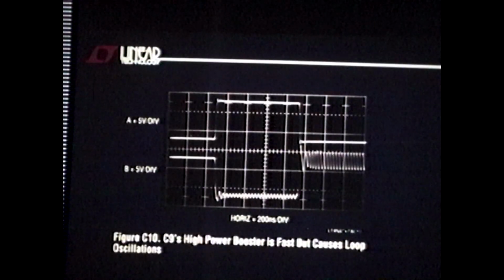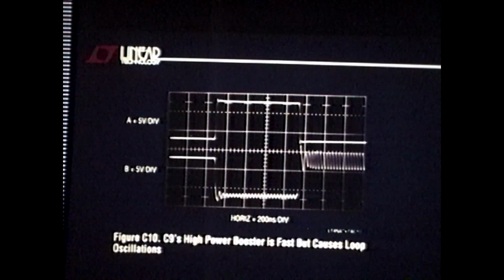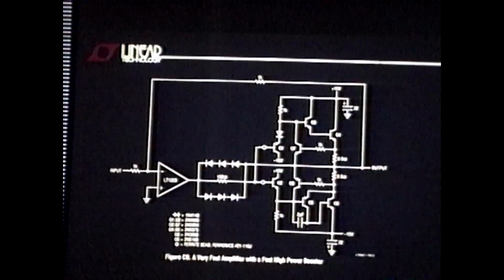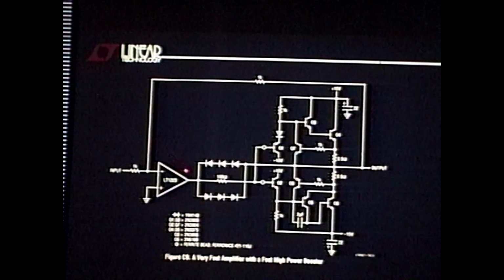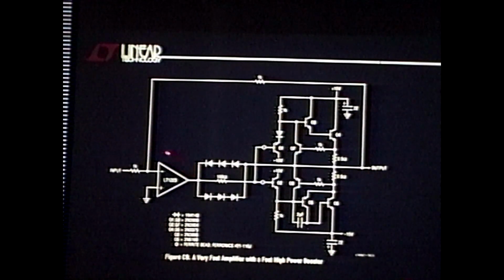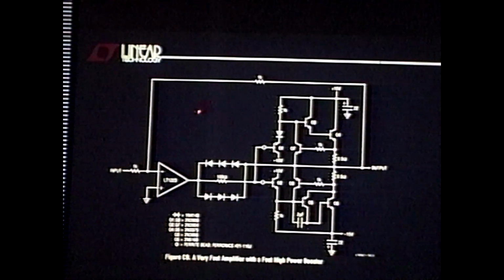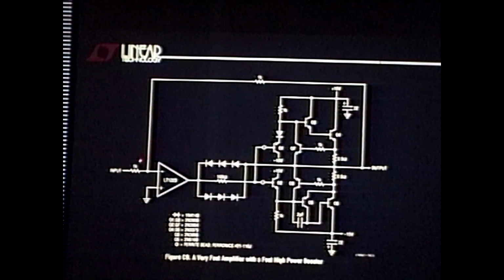So these waveforms, as ugly as they are, provide you very valuable clues to how to shut these things up. And if you remember the text circuit, the fix was the same here. Kill the gain bandwidth there. Perhaps a less expensive way to kill the gain bandwidth than adding a cap is to specify a slightly slower amplifier. Then the cap is, quote, free, unquote.